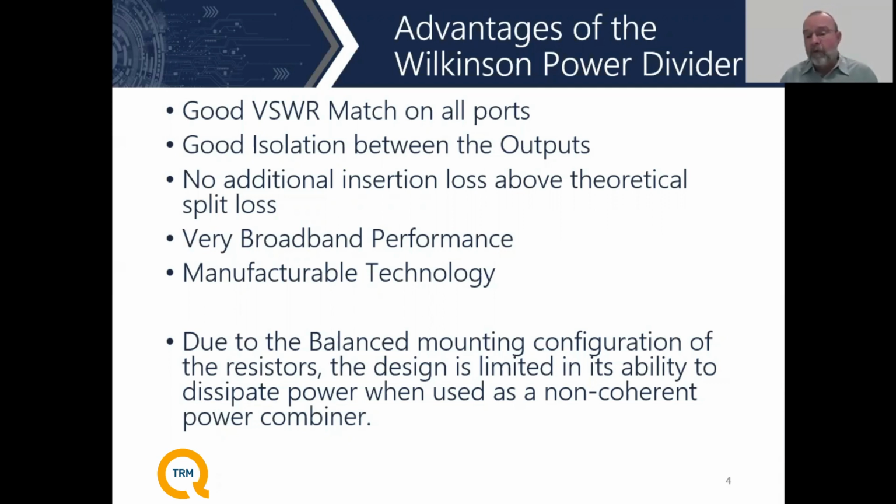There is a downfall of the Wilkinson divider, and it's only when it's used as a power combiner, which I've spoken about in the past. The isolation resistors in the design are in a balanced mode, sitting between two traces as opposed to going to ground, so you don't have a good thermal path out of those resistors. So when you're using these dividers as a combiner in a non-coherent situation, the power handling capability is limited. That is really the only downside of the divider. But for many, many applications, it's a wonderful device and does a great job.